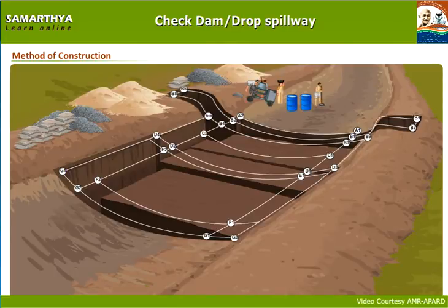The required 40 mm gravel and 20 mm gravel should be brought to the place of construction of check dam. The required implements like concrete mixer, water drums, iron baskets, concrete vibrator or rammer should be brought to the place of work. It should be established how many baskets of cement are in one bag.